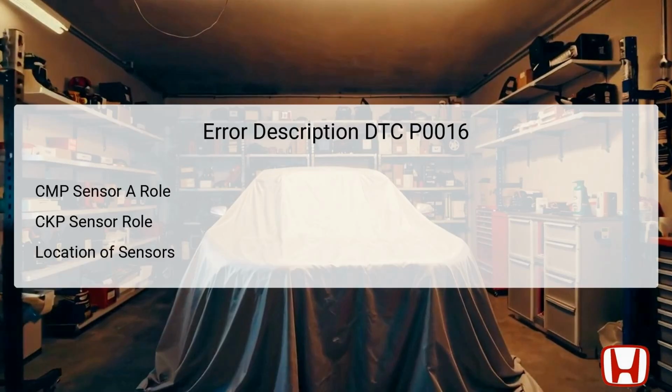DTC P0016 indicates a mismatch between the CMP sensor A and the CKP sensor. The CMP sensor A plays a vital role in determining the position of the intake camshaft within the engine. Located near the engine's intake components, it provides critical data to the engine control unit, ECU, for accurate timing.